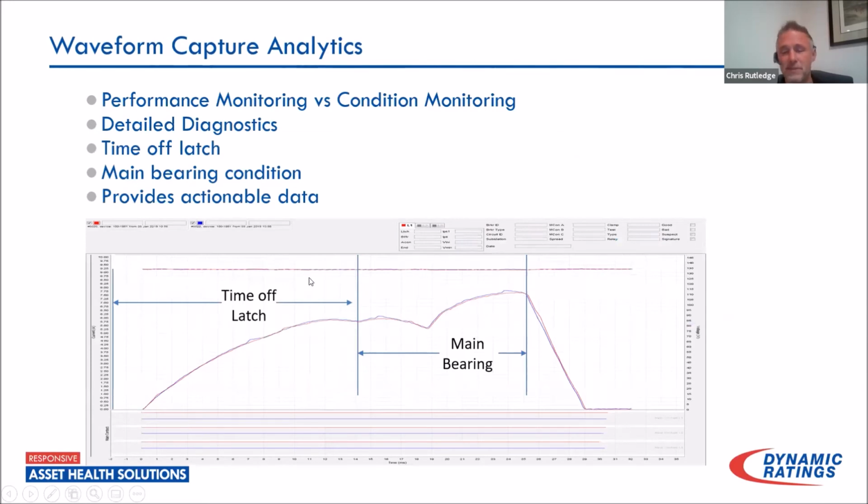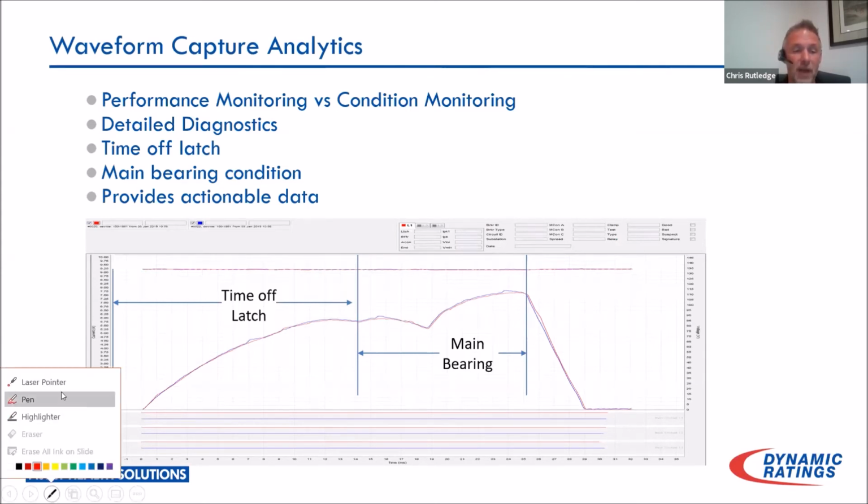So this was actually a field test that I brought with me, but again, a little more detail into what I mean when I'm saying latch and main bearings. Again, this first little dip is always going to be our latch, and then this is where that plunger strikes the buffer. But at this point, we should see that our main cam has started rolling the contacts open, at which point our A contact will open, and we should see de-energization of that trip circuit.